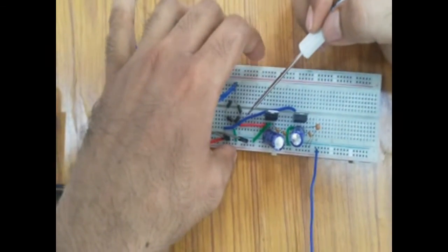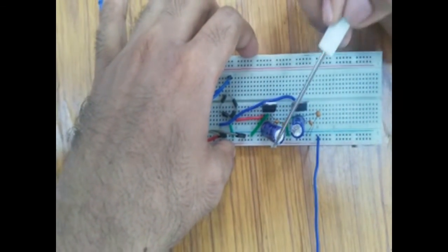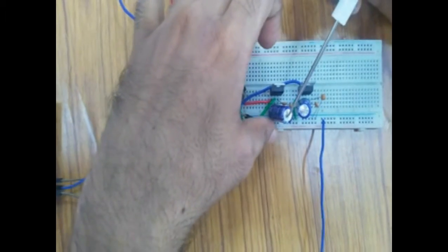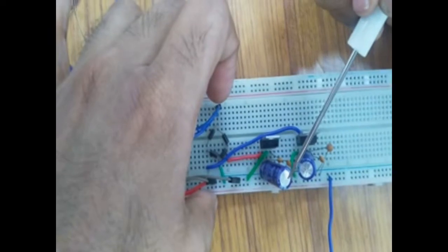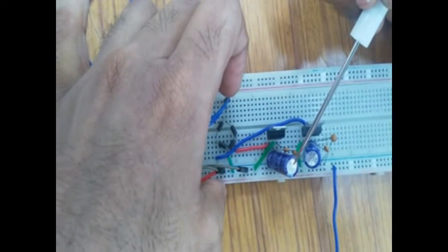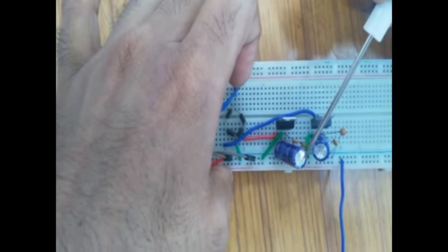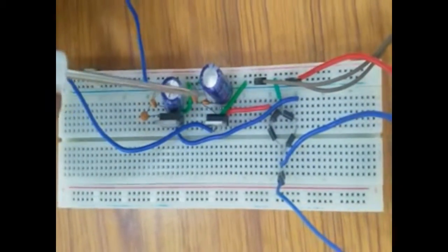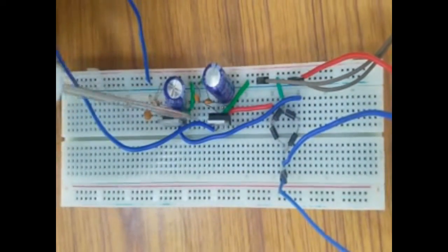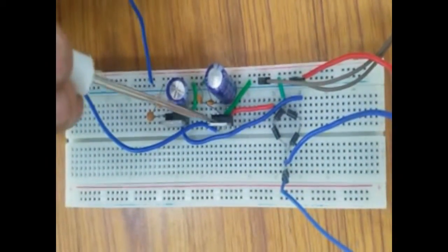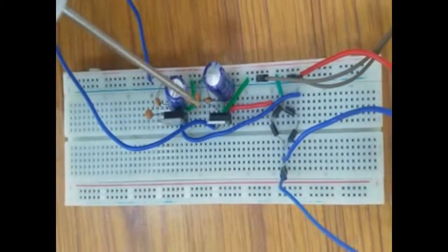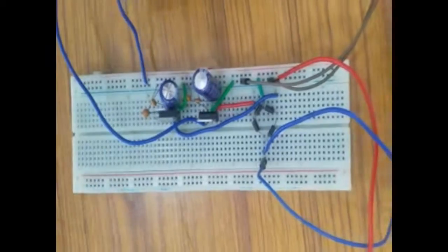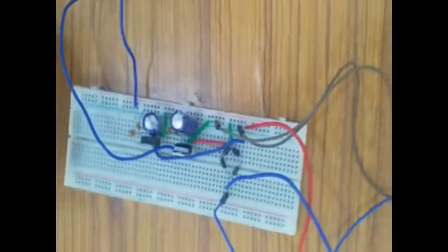The AC signal that is coming will be rectified, and the DC signal will come toward the filter circuit. This filter circuit acts like a noise filter, where the AC component and any unwanted signal will be filtered. Thereby we get a perfect DC signal, and this DC signal is given to the regulator circuit, the 7805 and 7905, so that the signal will be regulated. Now we will observe how it is working.